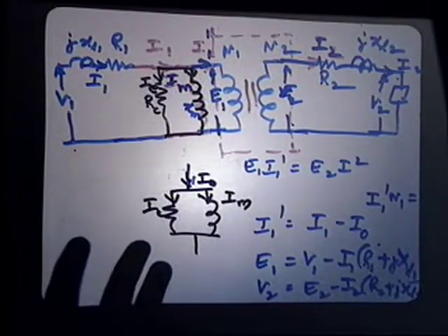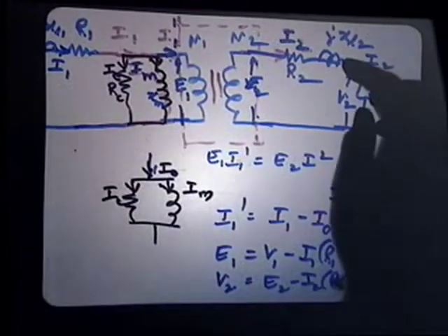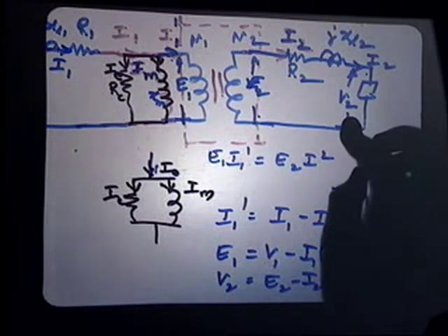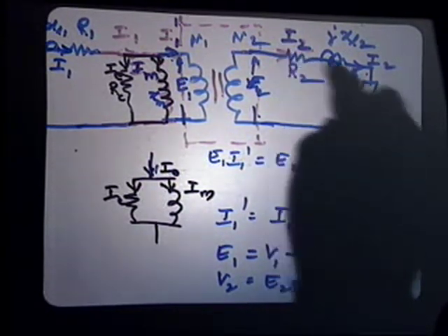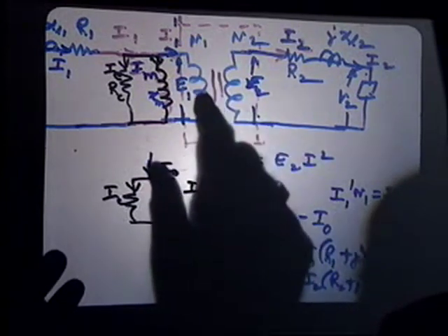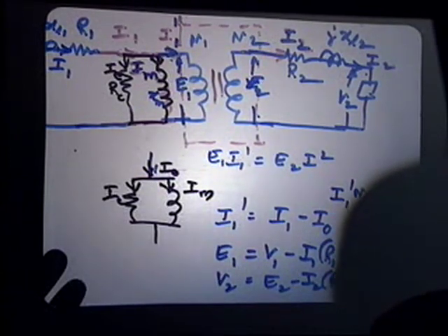So please read about the short circuit test as well. When you do a short circuit in the secondary, what is the mutual flux? It is 0, because the secondary will draw such a current to oppose all the primary MMF. So ideally it is a low flux, and the core loss is 0 or negligible.